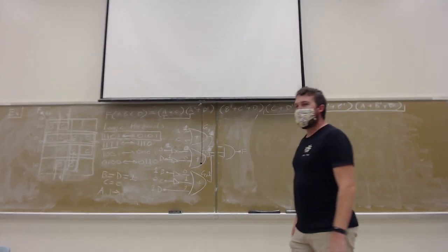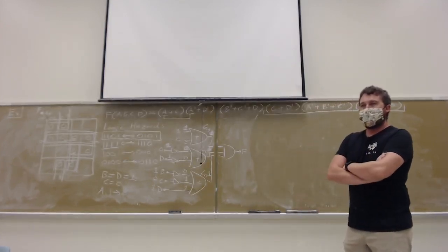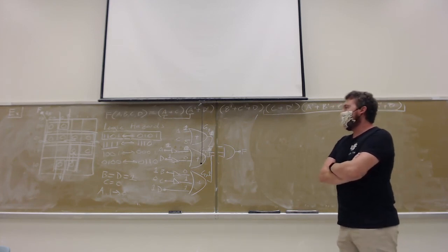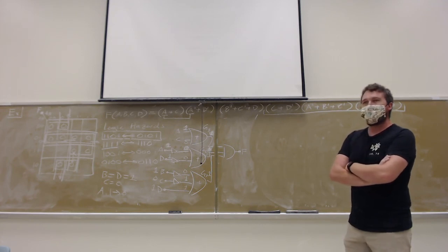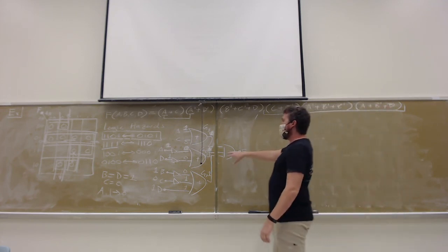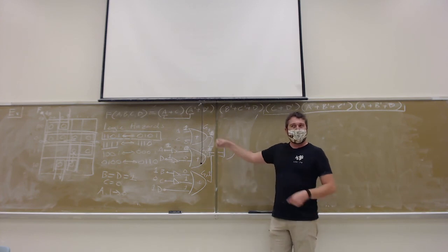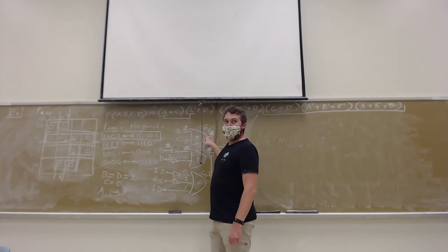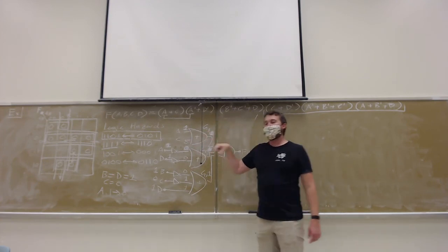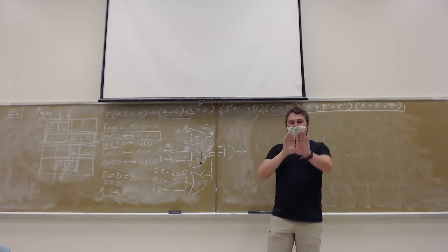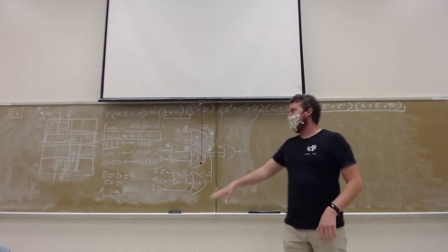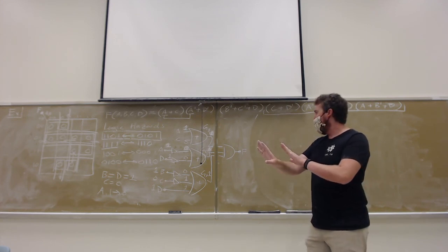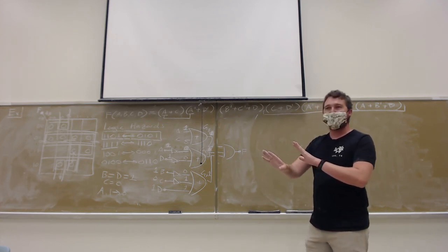Would it be quicker just to add a slight delay in the processing of the answer? Yeah, what you'll see a lot in practice. Remember that all this business of logic hazards assumes that all the propagation delays are the same, which they won't be. What you'll see a lot of times is people adding buffers or two inverters in between these gates to get the delays just right. That way the solutions are still optimized by the gates, but the timing works out, so you don't have those issues.